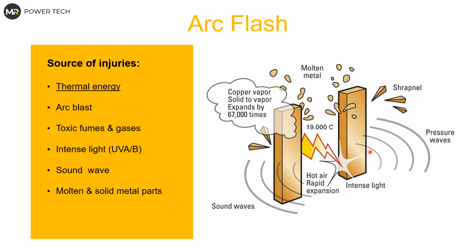And this creates a pressure wave, which was opening those doors that we saw in the video. The pressure wave can be so high that it can throw grown men a few meters, but that's rare. We can also see intense light, something like 12 million lux. In comparison, if you look directly into the sun, it's 100,000 lux, so that's 120 times more, and it can create temporary blinding.